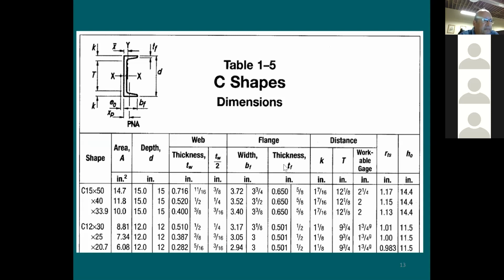Generally speaking, when you look here for all of this information, it says width, thickness, depth. You're going to see here two numbers, right? One number is going to be for the actual depth for design, and this is going to be for detailing. Look at this, thickness 0.52 or half inch. Which one should I use if I'm doing a design like calculation analysis? It's going to be this one. This one I'm going to be using if I'd like to develop a detail.